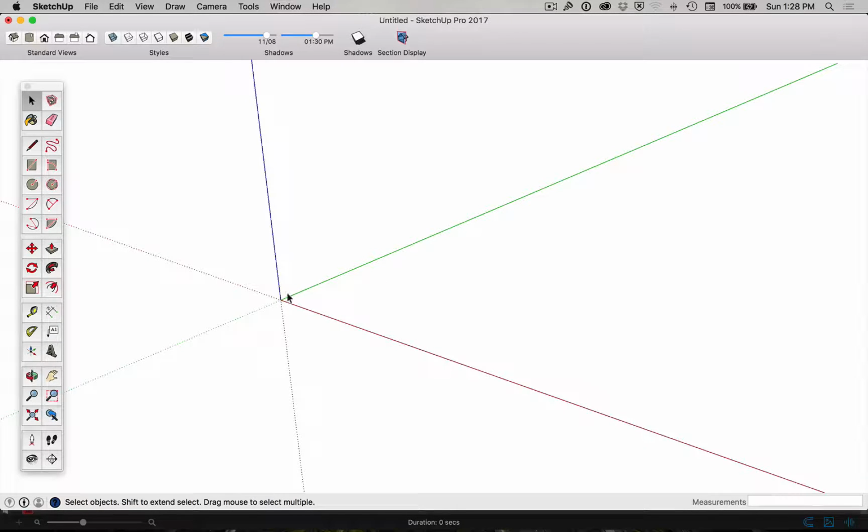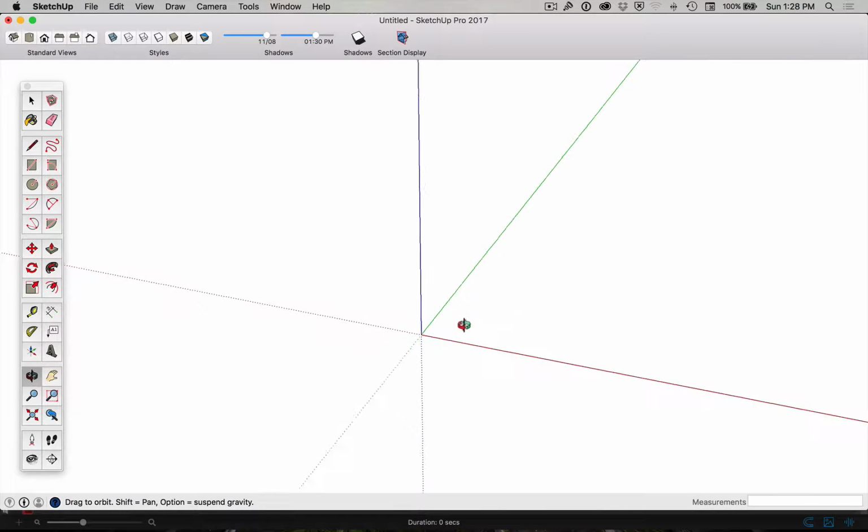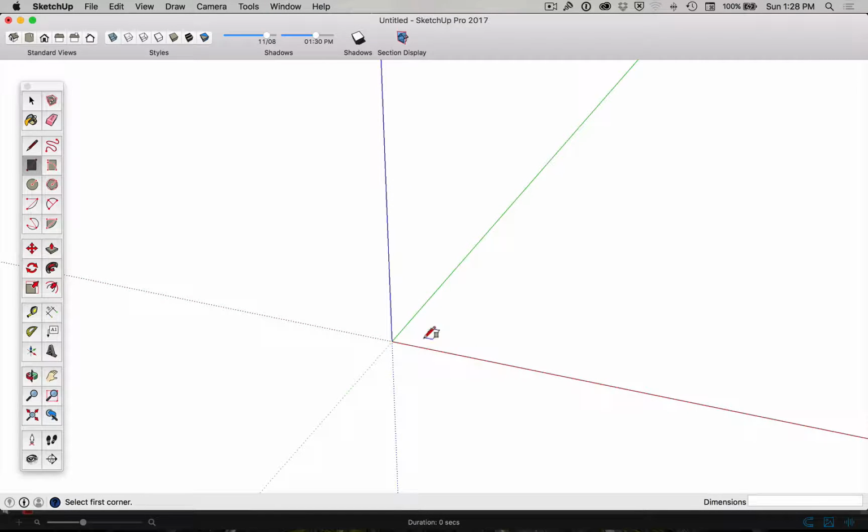When we start a drawing, we've got to think about what we're trying to achieve. In this drawing there are 4 legs, 8 aprons, and the top part of the chair as well. Normally what I would do is create the profile of the timber pieces before we do anything else. So in doing the profile, what I might do is just come in a little bit here and start with a rectangle, because our chair, we know, is 40 millimeters by 40 millimeters.